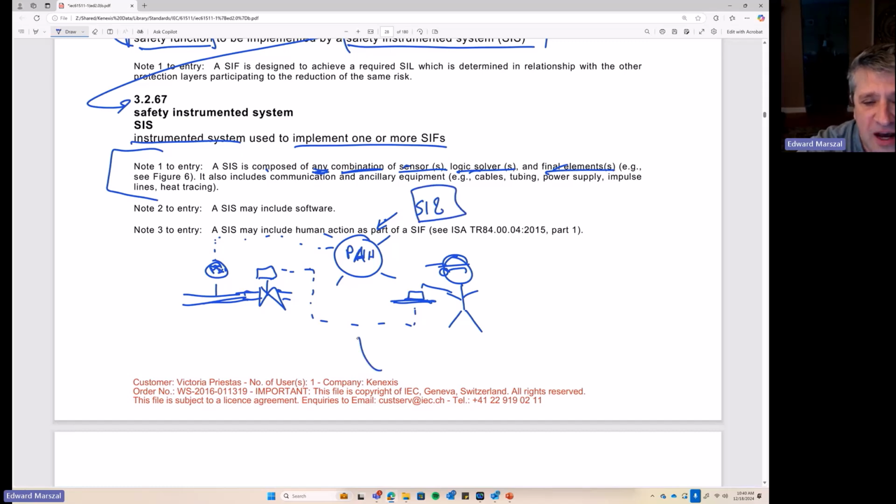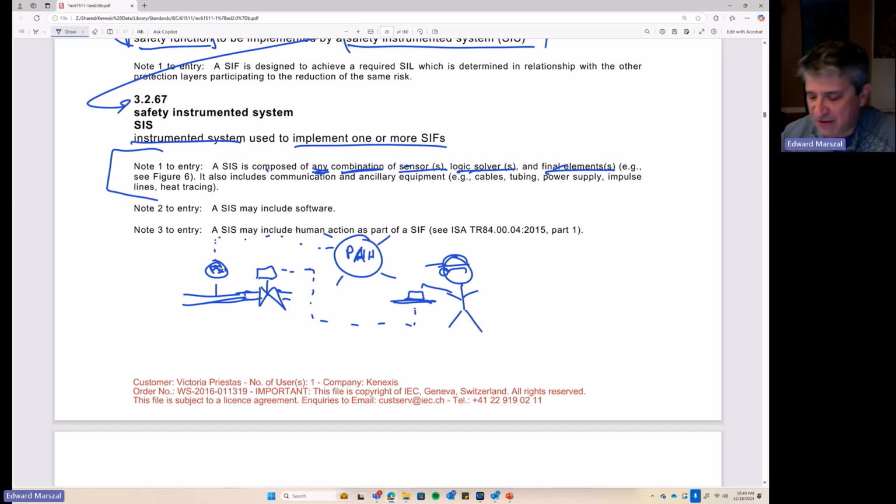I would design this part to API 560. Is that the valve standard? There are other standards for push buttons. There are other standards for valves. There are other standards for alarms that you would design to. But even though I wouldn't consider this a safety instrumented function, almost if you get a room of SIS experts together, they wouldn't call this a safety instrumented function.